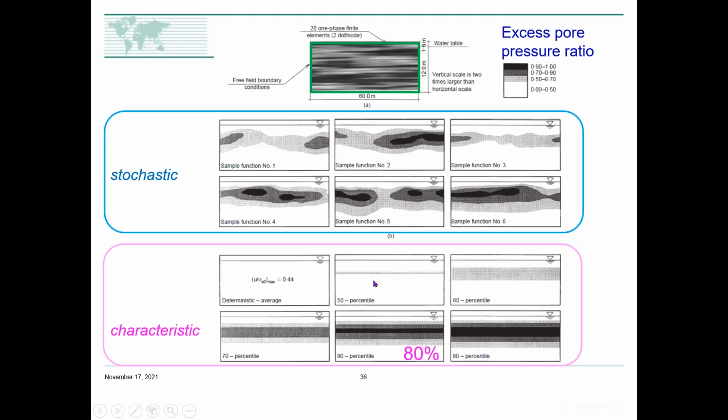Here we're going to pick whatever the state parameter corresponds to 50% of the soil is looser and 50% is more dilatant. Here we're going to have 60% more dilatant, 70% more dilatant, 80% more dilatant, 90% more dilatant, but in each case uniform. And it's now a question of engineering judgment, because this is how we're going to use our standard engineering calculation. What of those do you think best represents what is in the blue?